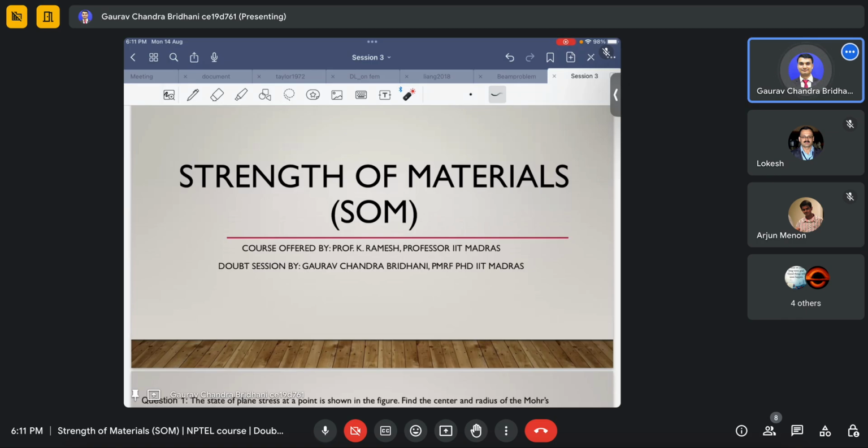And then we have seen principal stresses, how to compute principal stresses for the case of 2D as well as 3D, a general case of 3D. And then subsequently we have seen the components of stresses on some specific planes, like the octahedral plane. So we had octahedral normal stress and octahedral shear stress. We'll solve some problems regarding that, so that it will be helpful for you to solve assignment questions. That is what we will be doing in today's class.